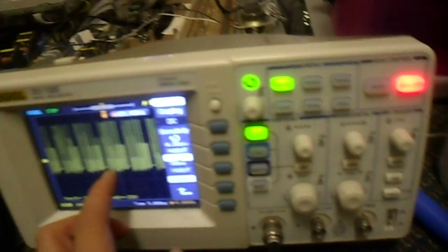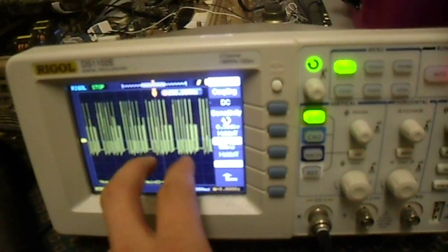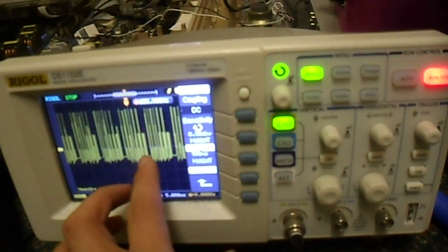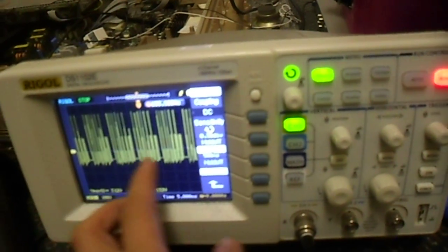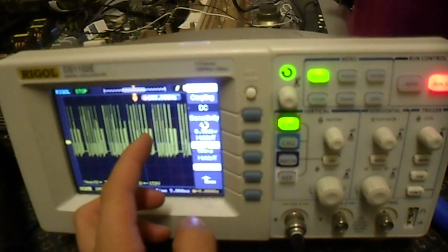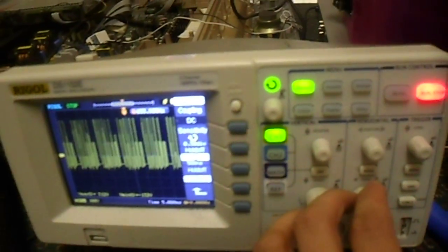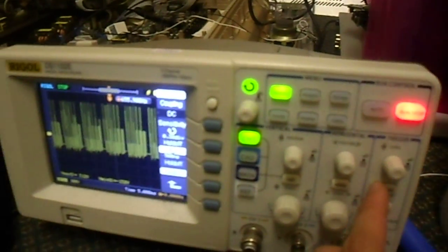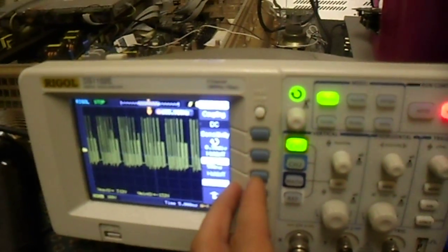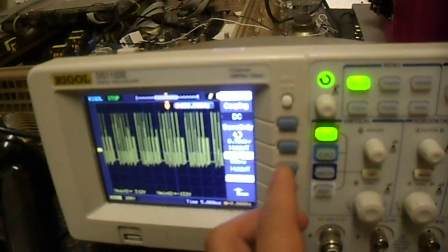Take a little single shot here and we see that it's about 2 divisions between the subfields. 5 millisecond division, it's 10 millisecond sustain, which means it's refreshing the panel 100 times a second, and it looks to be 7 subfields in each one, so technically this is a 700 subfield per second display, which is an odd number of subfields. We normally go with 8, but I suppose it's probably using uneven subfield widths.